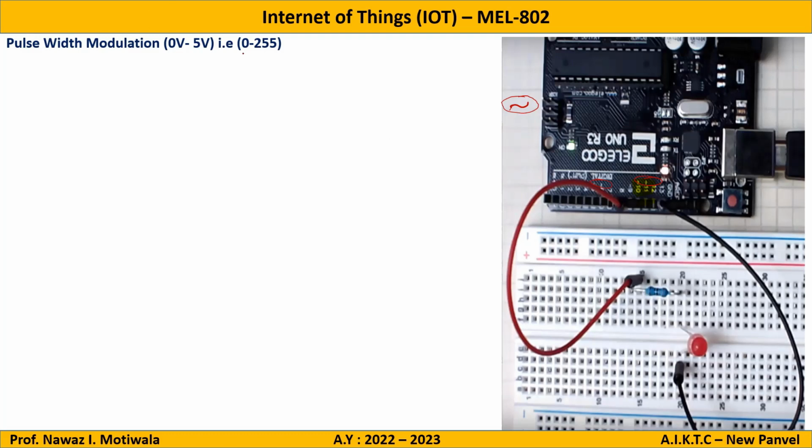Okay, now let us see how to write a program. So first step, as I told, is declaration of pin. Which pin of Arduino you are using. As it is only one LED, I will be using only one pin of Arduino. So I will just declare the pin. Let us say I am using LED 1 equal to 9. That is, I will be using the 9th pin of Arduino board, which you can also see is a pulse width modulation pin. So this completes step 1.